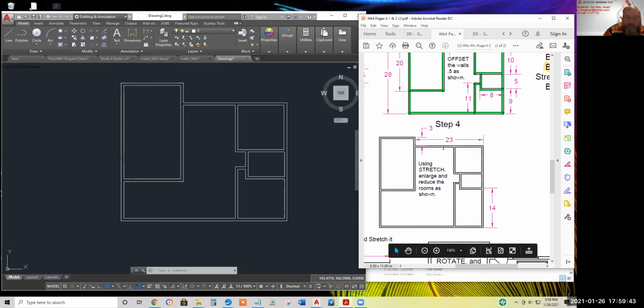But the crossing window has to go through these lines so that these lines will turn into rubber bands to stretch longer or shorter. So where the crossing window, crossing polygon, or crossing lasso, I believe, never tried it, where the crossing selection set goes turns into rubber bands.